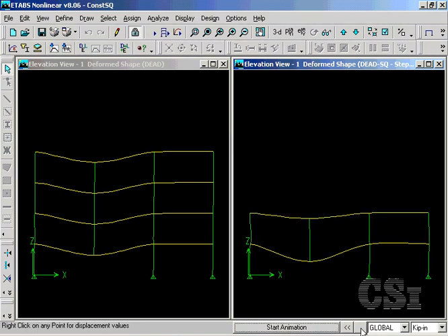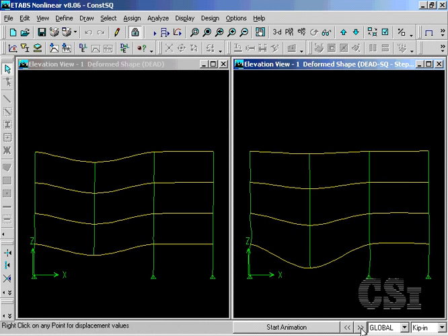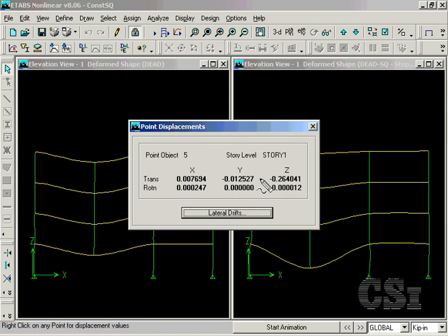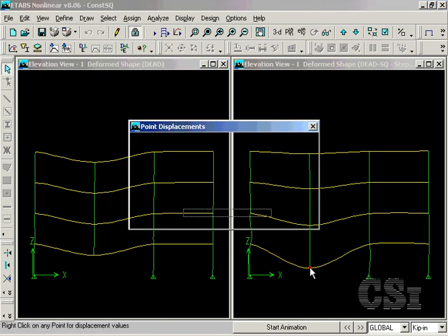Note how the displacement at the transfer girder location grows significantly larger than that of the model where no sequential behavior is accounted for. In fact, a right-click on the girder shows the displacement to be approximately 1/4 inch for the non-sequential case, while the displacement is more than double when sequential effects are included.